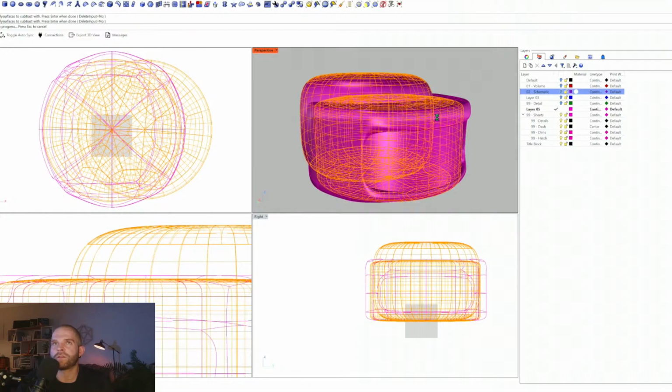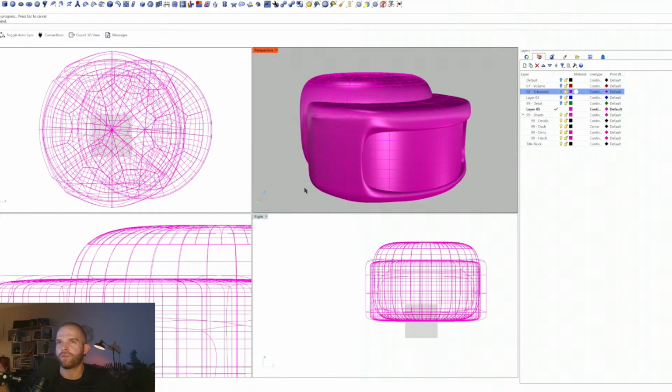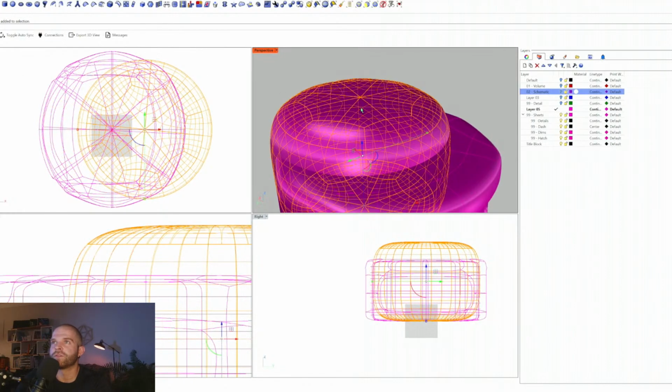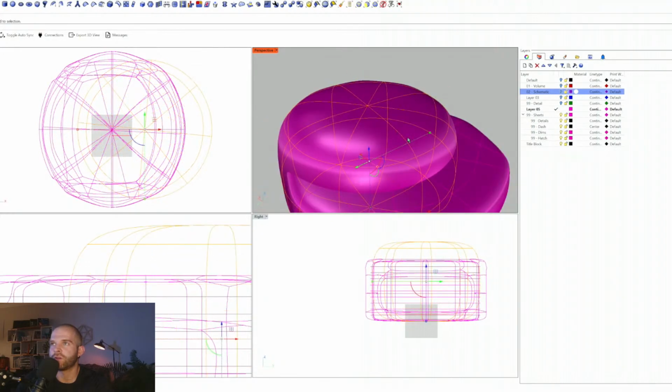And it's likely working because it's freezing. So if you wanted to do Booleans with SubD, I guess that's the way to go. You've got to do toNURBS so that you have NURBS. So you could do just a normal Boolean operation, Boolean difference, Boolean union, whatever. And then go back to SubD. No, just kidding. Boolean difference failed. Well, that's probably because there's way too many faces going on here in a weird way.